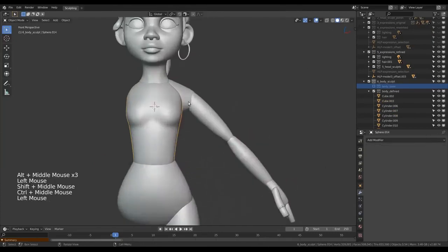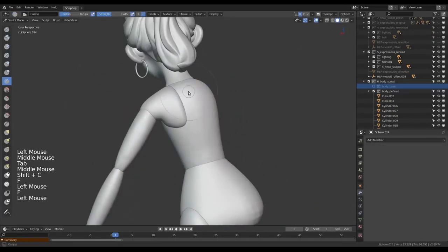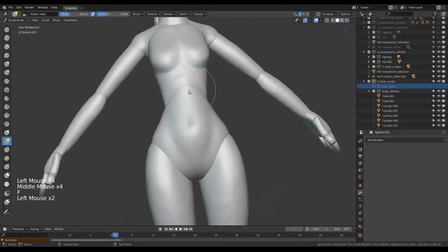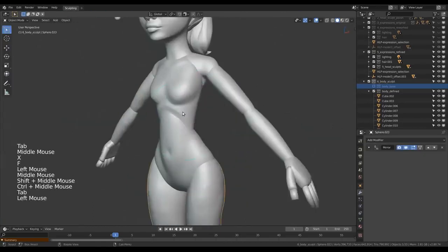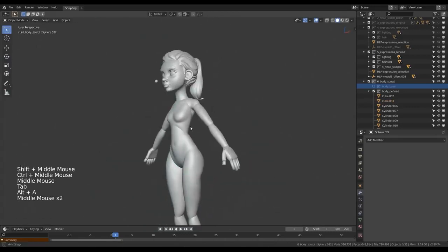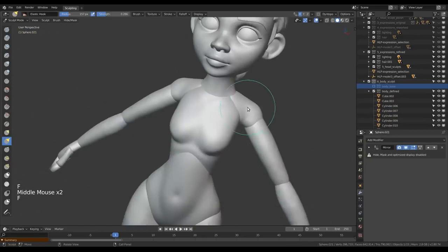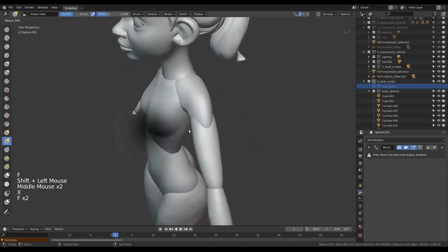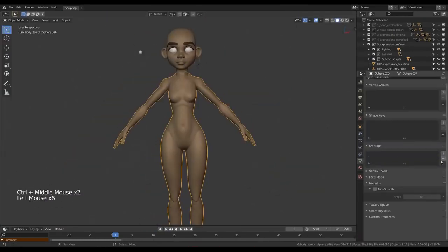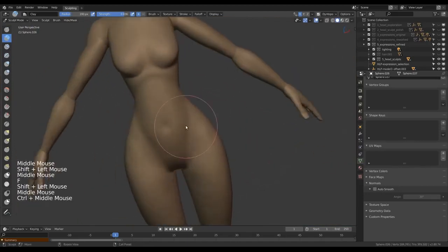It's good to sculpt the character in a resting pose, like a T-pose, with very straightened and angular limbs, or in an A pose, which is more relaxed with, for example, 45-degree arm angles. The T pose is a better resting pose for later rigging and animation, while the A pose will give you more accurate deformations in the animation if the character is leaning more towards a realistic style. Keep sculpting and refining the proportions and shapes until you are happy before joining everything together.